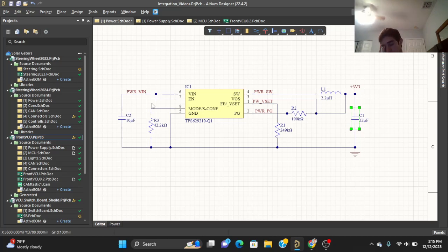So why are we choosing capacitors with such high voltage ratings? That is because of something called DC bias. When a true DC voltage is placed across the capacitor, it's going to decrease the effective capacitance of that capacitor. I'm not going to go into much on why. You can do your own research on that. But it basically means that we want to choose capacitors with much higher voltage ratings in order to mitigate that effect.